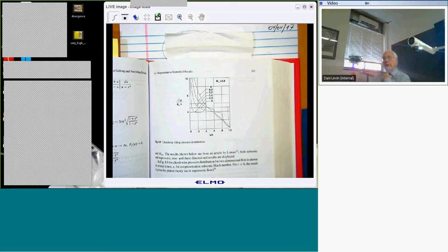So piston theory, when you read the literature, they say, well, you can use that at high Mach numbers, and that's true. But you can also use it at high frequencies, and that's in that paper as well. If the non-dimensional frequency is high enough, piston theory gives you the right answer, okay? And high frequencies, the duality between time and frequency, correspond to short times.